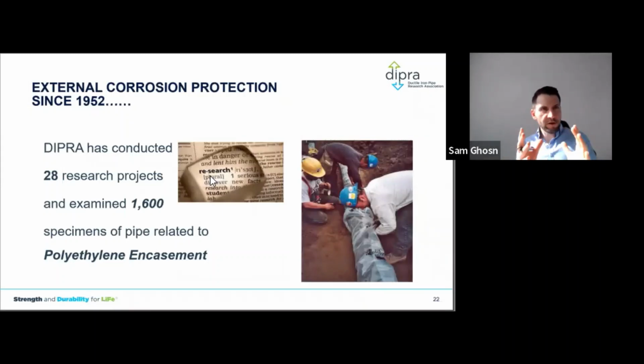So the electrolyte around the pipe is a homogeneous electrolyte, same in nature, where you don't have anodic and cathodic areas around the pipe. So you create that atmosphere or environment around the pipe that is actually consistent and will control corrosion for many years. Because corrosion will always happen. It is a reaction of a metal with its environment.